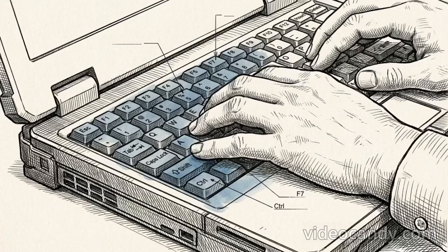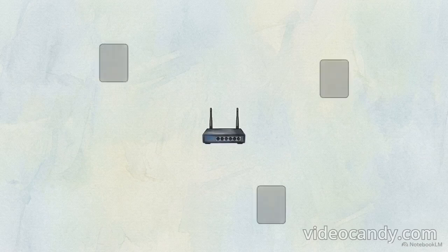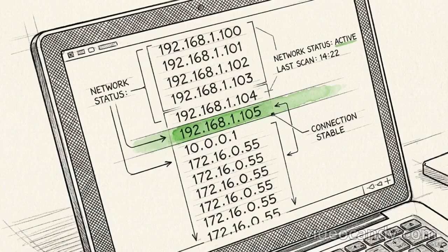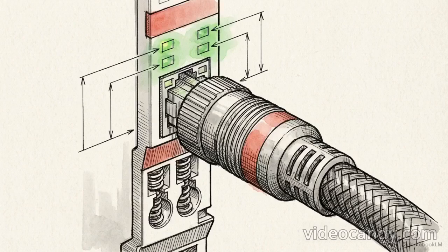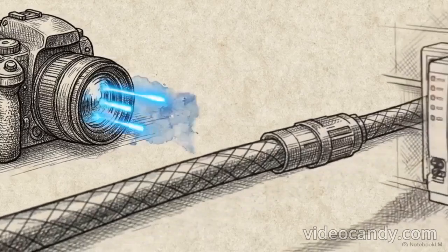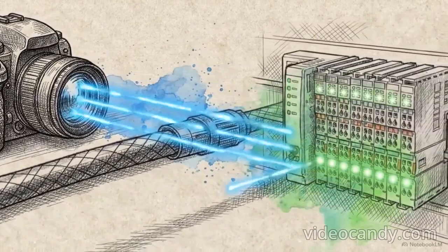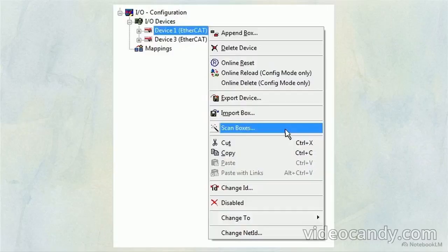This Add Route window shows how an engineer inputs destination data to establish remote connection routing. The engineer can manually enter a known host name, IP address, or AMSNet ID. Alternatively, performing a broadcast search will ping unknown Beckhoff devices on the local network. Successfully locking onto a target transitions the setup from a localized software instance to an active connection with the physical machine, enabling device discovery.